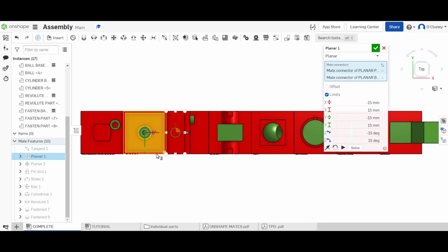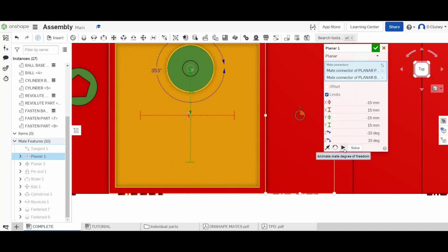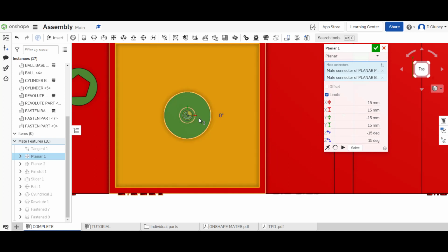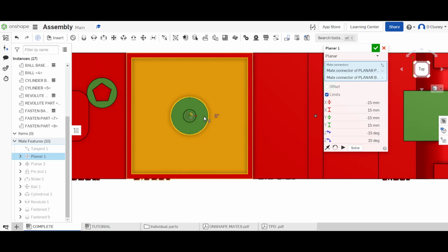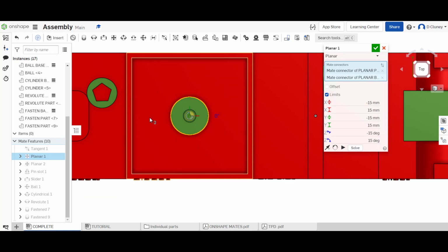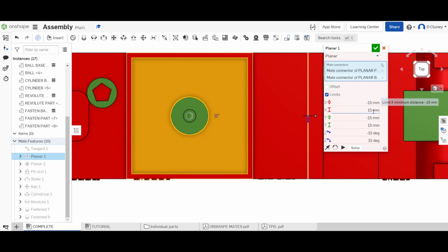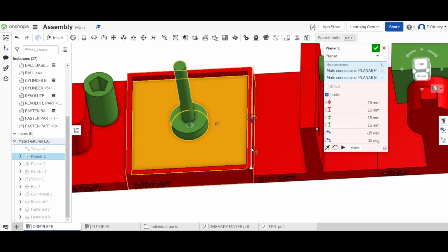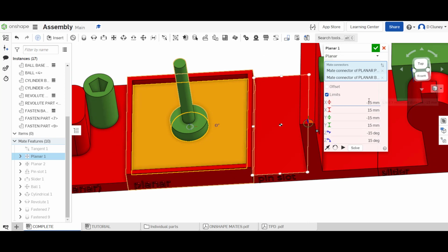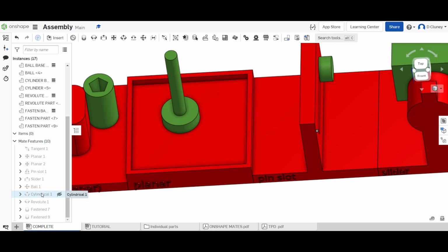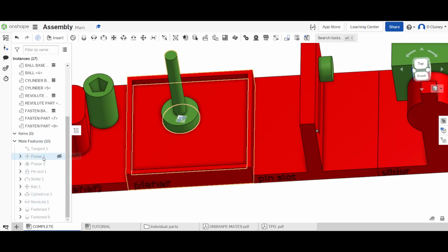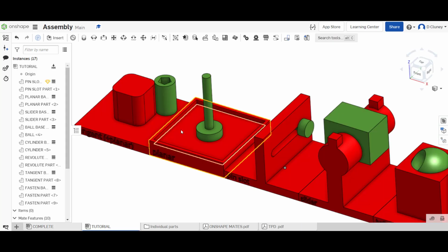And what we've got, if we look above and click on the play, it's allowing that to move 15mm from that point, to the right, to the left, to the back, the front, and so on, because I've set these here. So I've got 15 in basically the X, Y and Z, the minimum and then the maximum movement. And we can look at setting them on ours in batches, and you see how that's affected. So I'm just going to reset that one, just in case we need to look back at it.